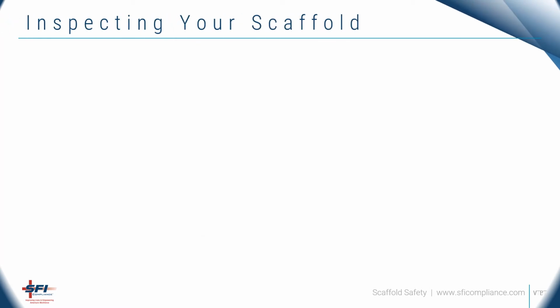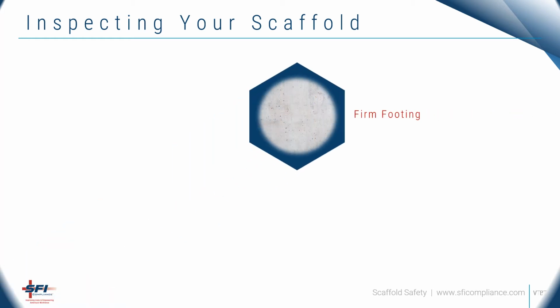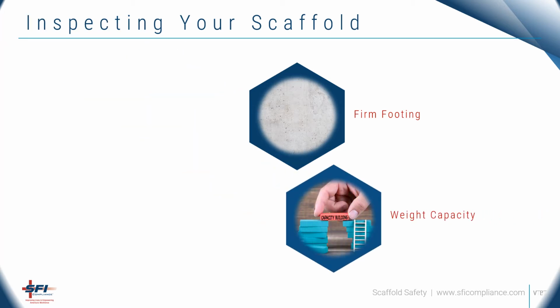A scaffold must be inspected prior to each shift. When inspecting your scaffold, check for these things. Scaffold must be erected on firm footing, like smooth, strong concrete, capable of carrying 4 times the maximum intended load. Boxes, barrels, loose concrete blocks, or brick must not be used to support the structure. Consideration must be given to the weight the scaffold is to carry. It must be capable of supporting, without failure, 4 times the maximum intended load.